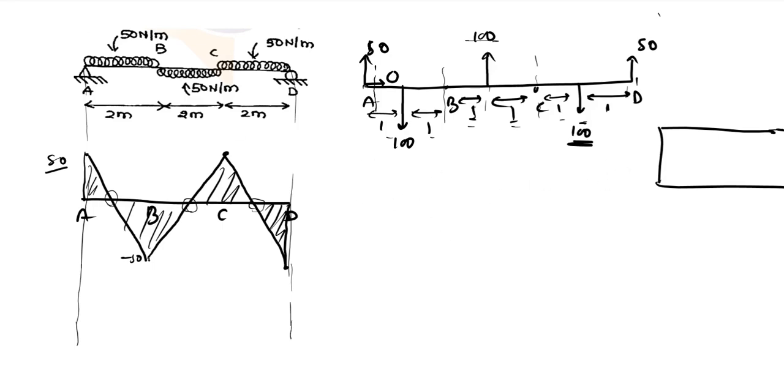So yeah, let us calculate the bending moments at these points also, because we know that at this point the shear force is 0 and the bending moment is maximum. If you are considering forces on the left, consider clockwise as positive and anti-clockwise as negative, and on the right, the opposite is true. Clockwise is negative, anti-clockwise is positive for the bending moments.